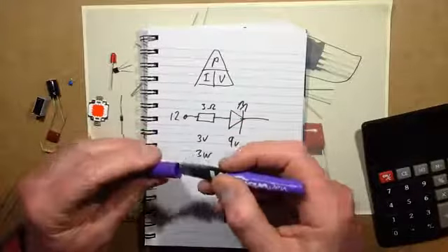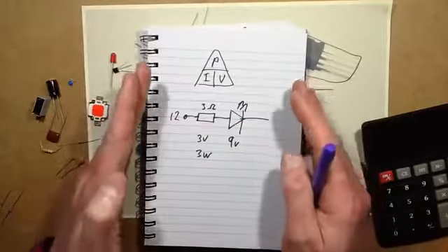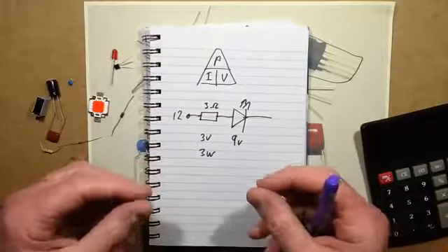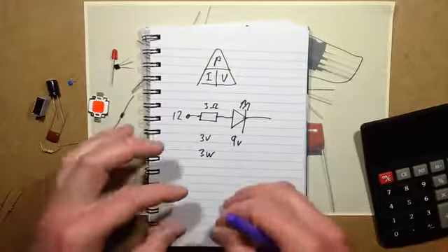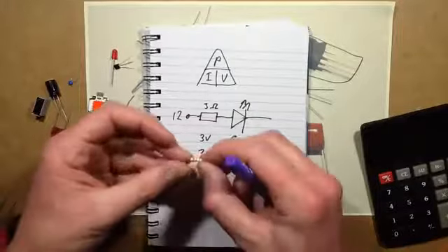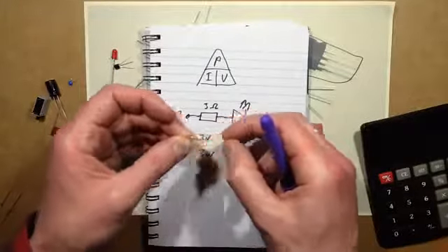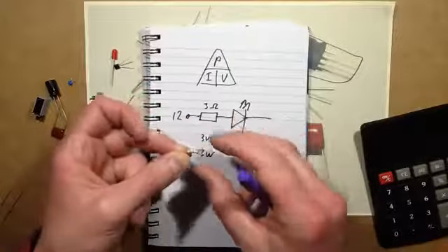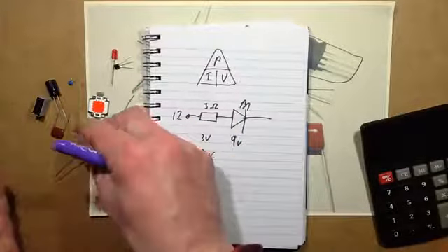You often see resistors that have just been pushed too far on printed circuit boards. You know, they've been designed and they've said, I need a 1 watt resistor. They use a 1 watt resistor, and instead of a nice colour code, it's basically the whole thing is just brown, and the circuit board shows heat round it as well. So it's good to dissipate, get rid of that heat.